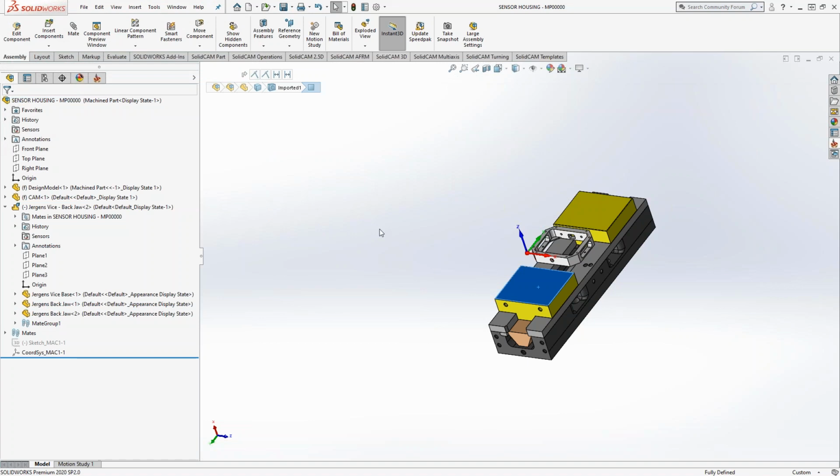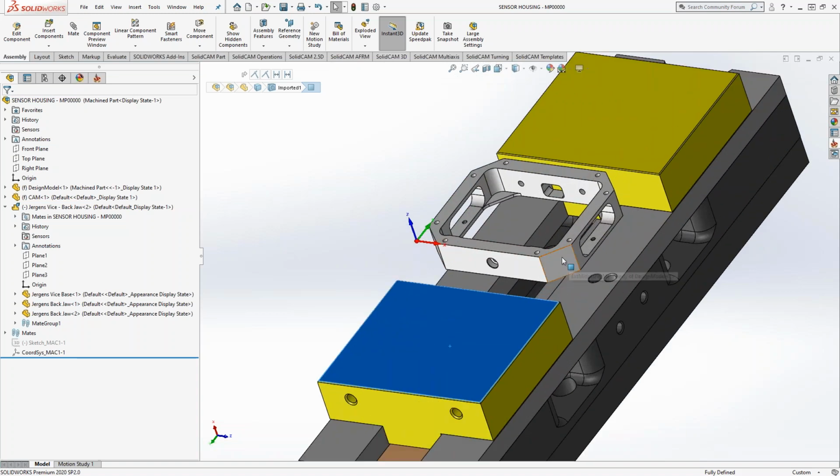Correct, yeah. I would always say you never want anything in here to be anchored or stationary unless it itself is something that doesn't really matter where it is in space. Like for instance, my target solid is what I brought in inside SolidCAM. So I kind of don't want that to be floating in space. I want that to stay relative to wherever I put my Mac position. But since this guy's anchored in space, I want everything relative to that.